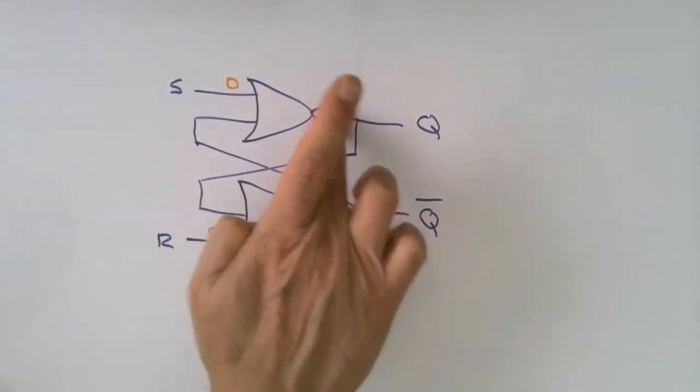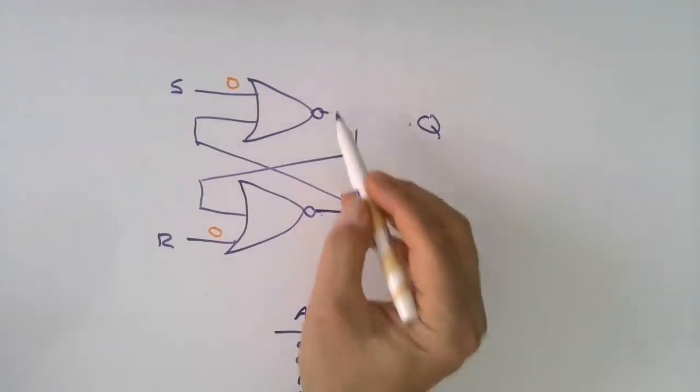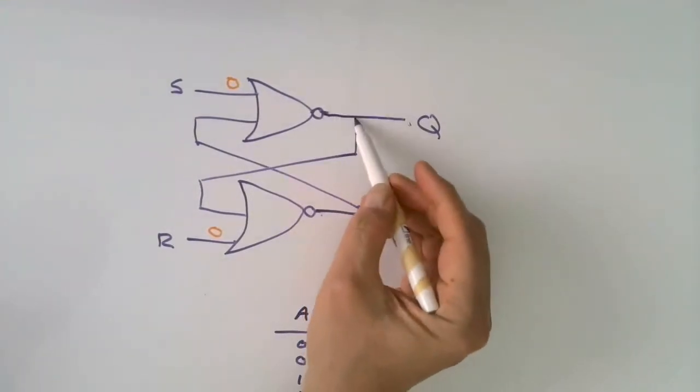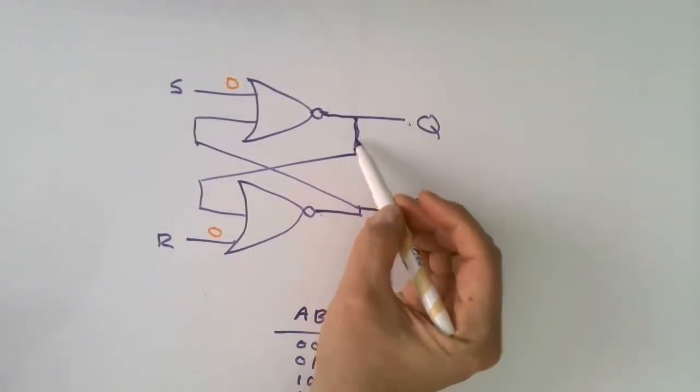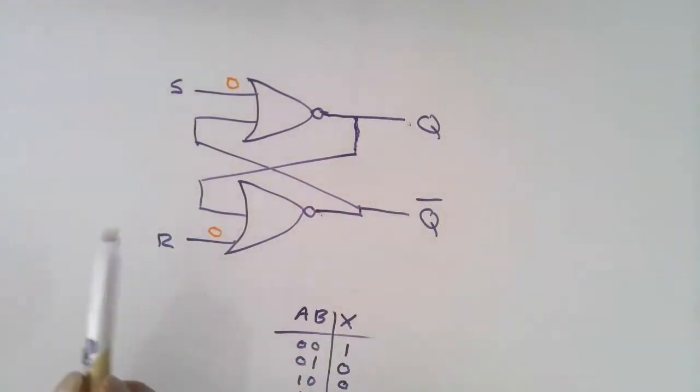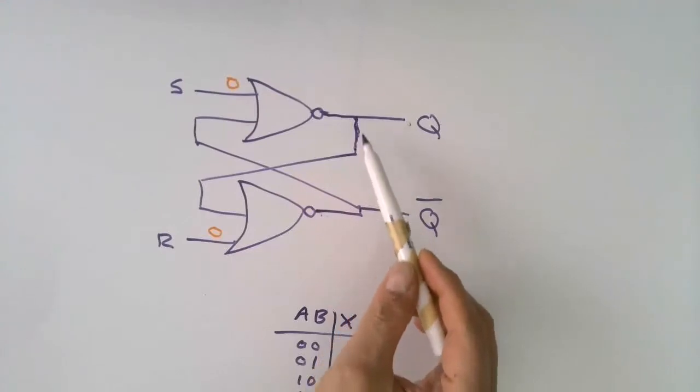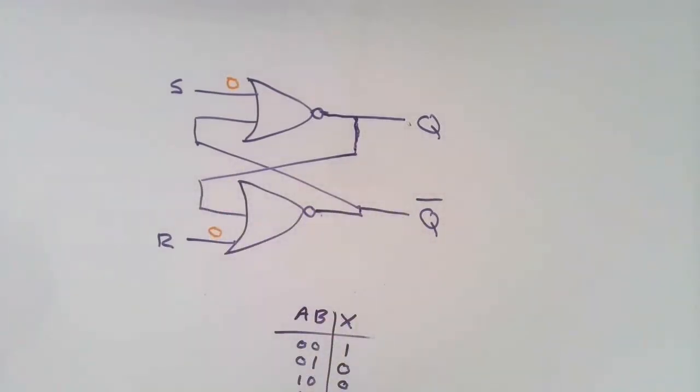So what does the inside of an SR latch look like? Well, essentially what it is, is 2 cross-coupled NOR gates. You can't really have a method of storing data or having what is called sequential logic, which is clocked logic, without taking the output of one device and going to the input of the other.